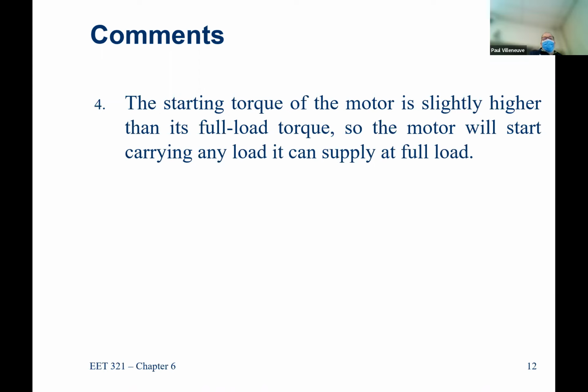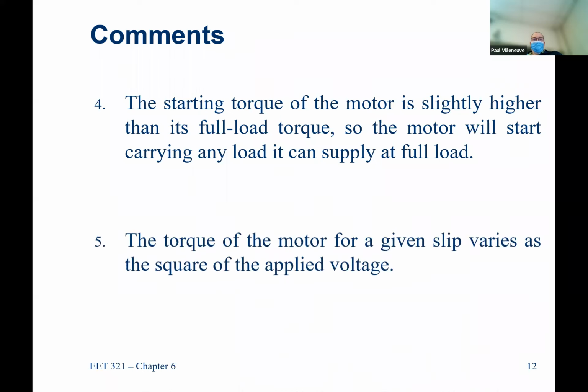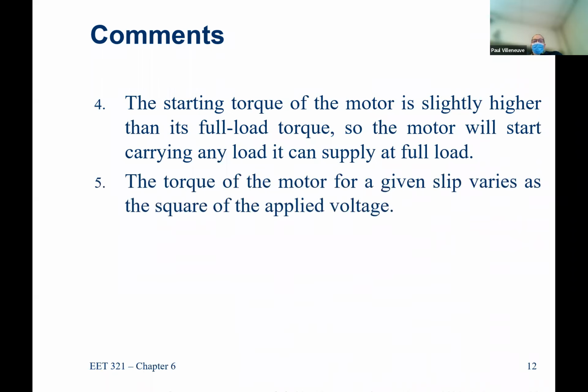Yeah, there's a lot of energy there. Most people don't realize that there is a little valve on the bottom of even cheap air compressors, because it's regular air, and as you compress it, what happens? The condensation in the air compresses and actually turns to water. Before you know it, you've got a ton of water in the bottom of your compressor. So, food for thought. What's that? Don't blow up your garage.